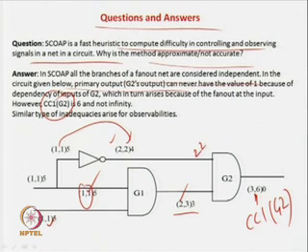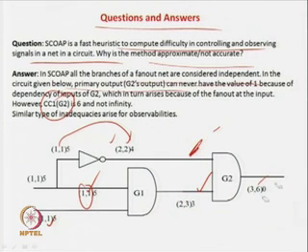So, how difficult is it to get a 1 over here? It is the minimum of 2 and 2 plus 1, that is 3, and again how difficult is it to get a 1 over here? It is the difficulty of getting a 1 at this one, this is 2. How difficult is it to get a 1 at this net is 3 plus 1, it is 6. So, to control this net to 1, we have the value 6.